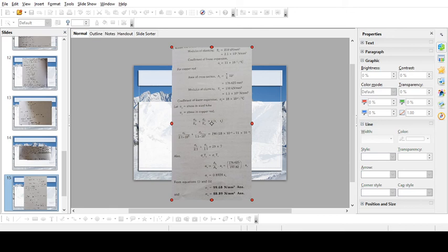Next, we have also discussed temperature stresses in a simple bar. If yield is not there, then compressive strain is alpha T, the stress is E alpha T, and the compressive load is A E alpha T. If a yield of delta is permitted, then the compression is L alpha T minus delta, the strain is alpha T minus delta by L, and the temperature stress is E into alpha T minus delta by L. In this manner, we calculate the values when exposed to temperature.